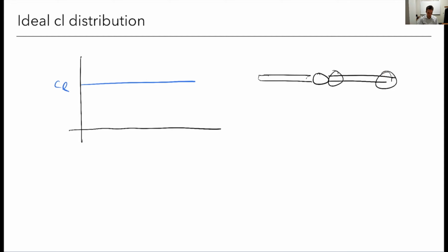Well, in an ideal world, let's say this tip and this tip stalled at exactly the same time, then I'd still be okay and I'd be balanced. But what's going to happen with tip stall is, because of any slight asymmetries in the flow, one's going to stall at some different instant than the other. Now I've got this big imbalance. I've got a lot of lift on one side versus the other. My airplane is going to roll. I'm going to have a strong rolling moment. That's going to be really undesirable, right?